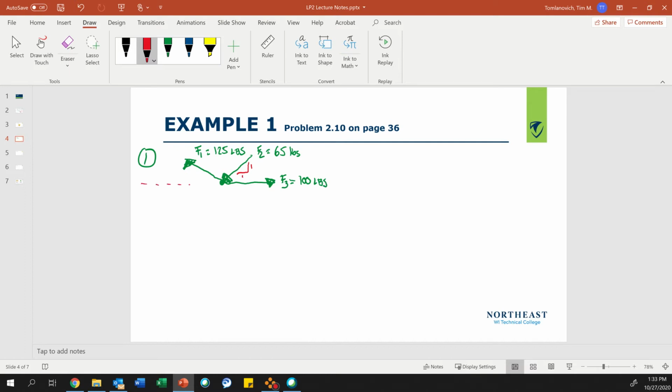Okay. And then they give you an angle of 25 degrees for F1 from horizontal. So the first step is they call this a free body diagram. All right, so step 2, we need to break everything into X and Y coordinates. Let's start with F1. Knowing trigonometry, the cosine is adjacent over hypotenuse because F1 is the resultant of that right triangle, and then sine is the opposite. So this is why it's important that you understand trigonometry and how to convert resultant forces into rectangular components.